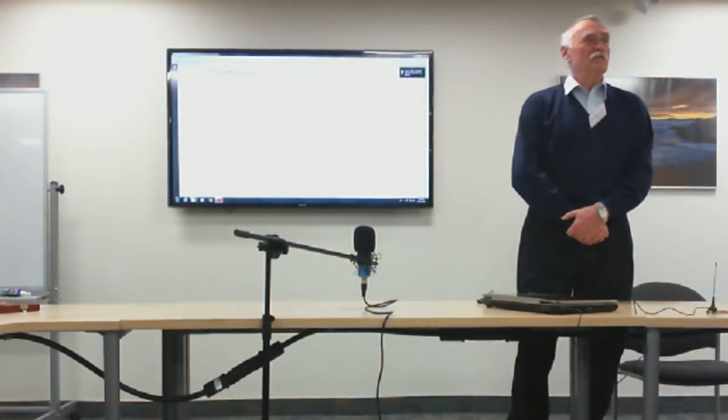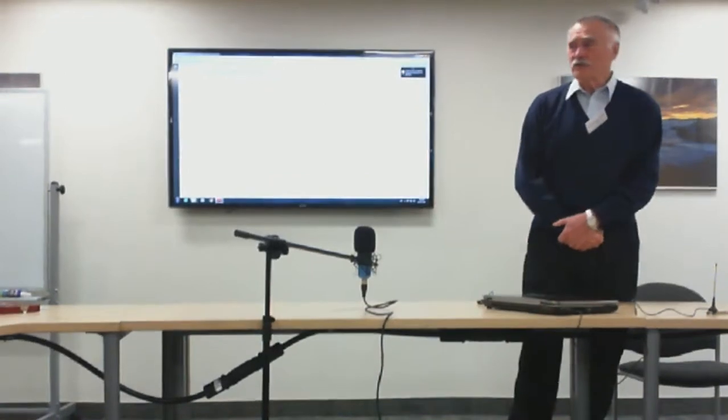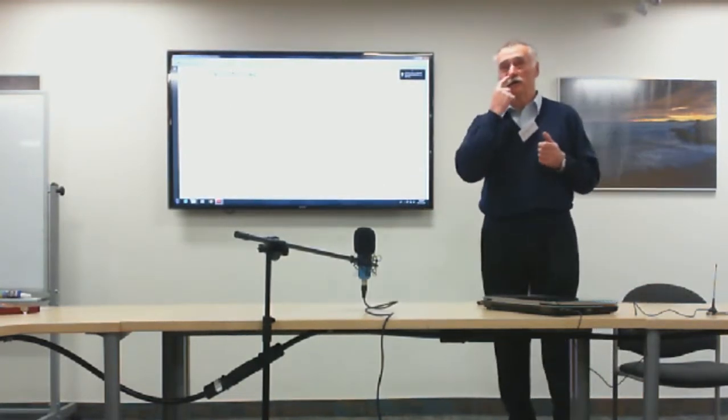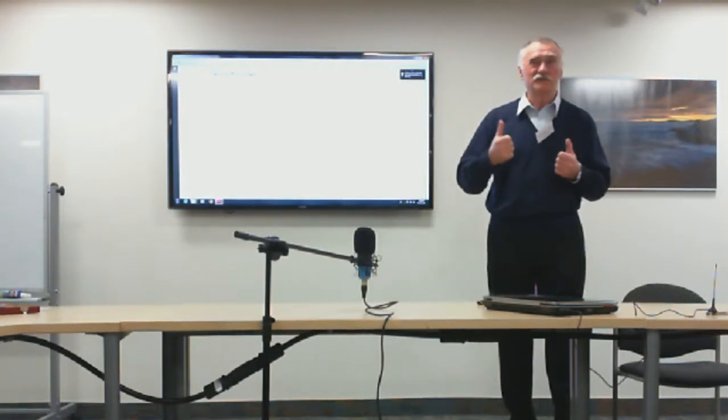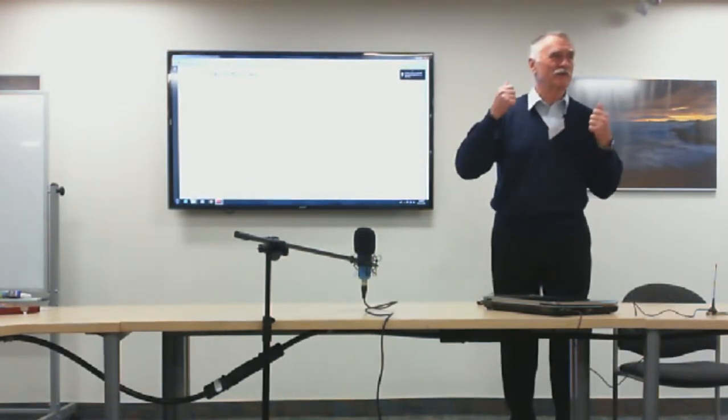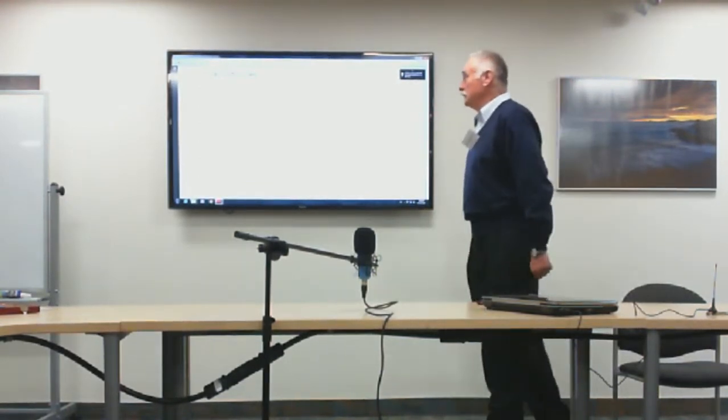So this is widely being abused, and if you read through, say, the American ham radio magazines, most amplifier manufacturers quote about their amplifiers stating that my amplifier can deliver legal limit. Meaning if the legal limit is 1 kilowatt, I sell you a 2 kilowatt amplifier and you are legal, because 2000 over 1000 is still just twice the power. 10 times log of 2 is still just 3 decibels off, that's all. So that's really an odd thing.